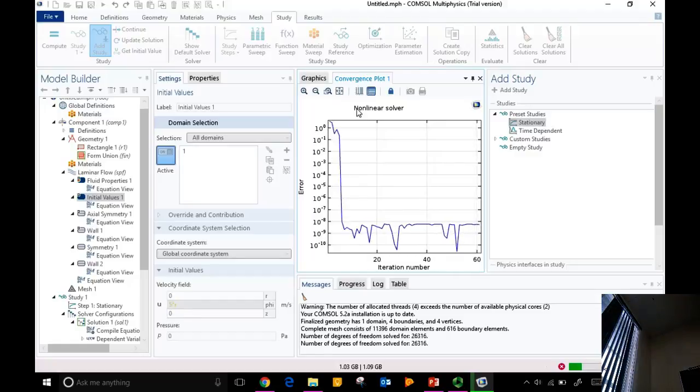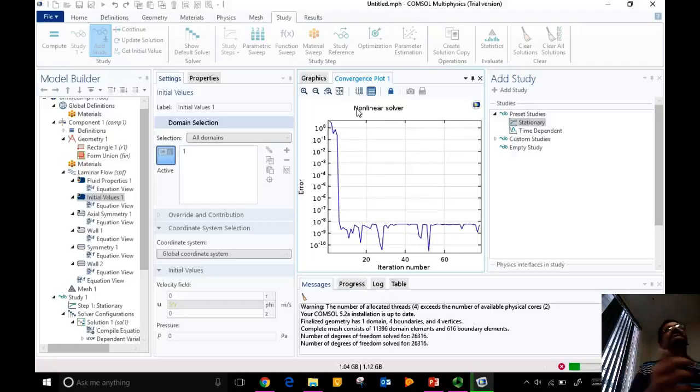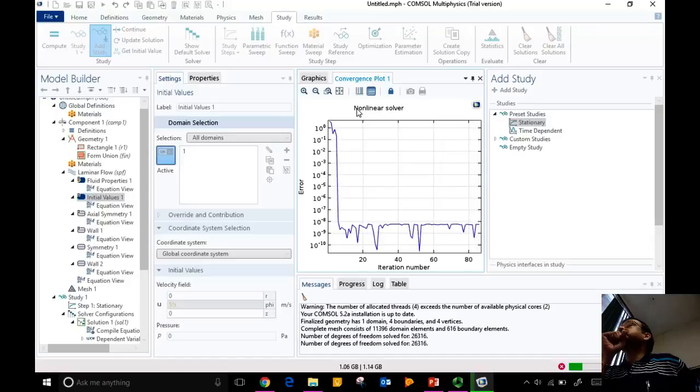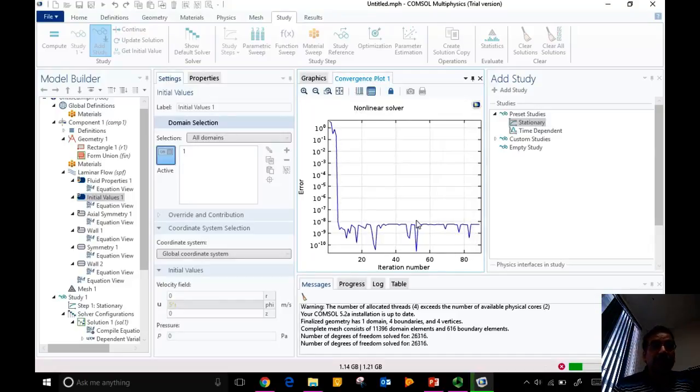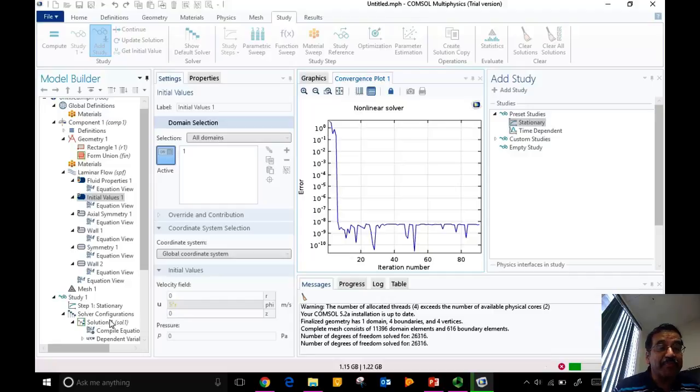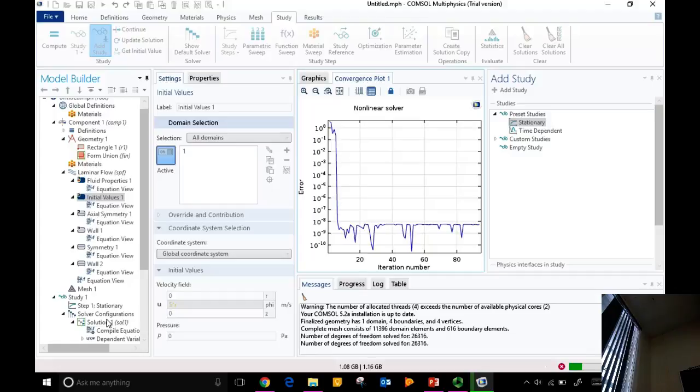So that's not going to work. The convergence plot is with a linear line in between. It should have stopped there. But if the tolerance is somewhere here, it will say it doesn't match, so it will just keep on iterating. And it is now at the noise level, round-off error, 10 to the minus 9. Can't we change the tolerance requirement? You can. You need to figure out where it is. I haven't prepared, I didn't search for it this afternoon. But let me fix this problem first.